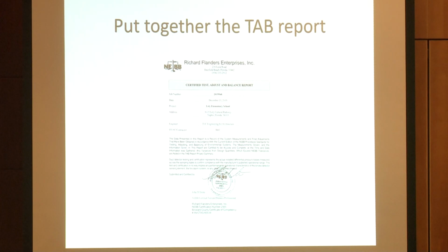More and more we're making it mandatory for the control valve manufacturer to calibrate it at the factory, and we're making sure that they have to document and certify that. But for the last couple of years, we've been finding that about half of the time they're not calibrated at the factory. So when they're not, it's still our responsibility to make sure that it's done.